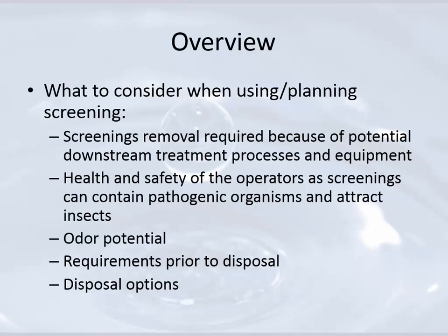What to consider when planning how you're going to use your screening. Screenings removal is really stinky. So not only do you need to look at the health and safety of your operators, there's your odor potential, and you pretty much have to get it out of there before you can dispose of it. And you have different disposal options depending on what your coarse or fine screens are.